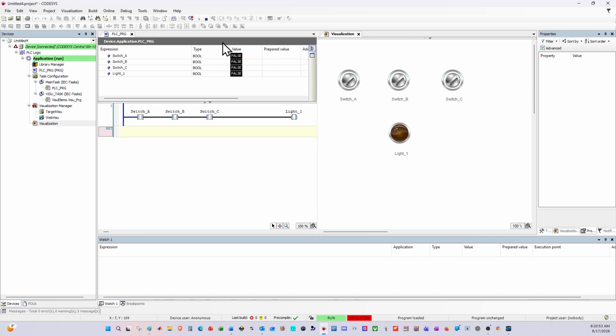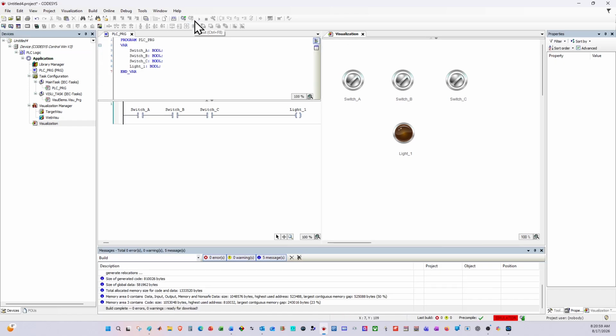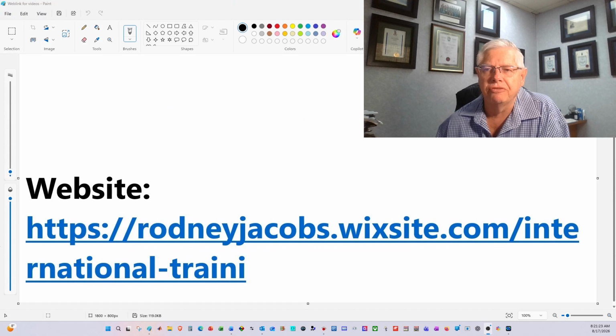When we finish, press the stop button at the top, and that will take us out of the simulation, and then we can actually log out. And now you can start off and change your program or do a new program, do anything that you want to. It's going to be perfect. And that was our first excursion into ladder logic programs. And we created a simple circuit that had 3 switches in series with each other, and every one of the switches had to be present in order to switch on the output.